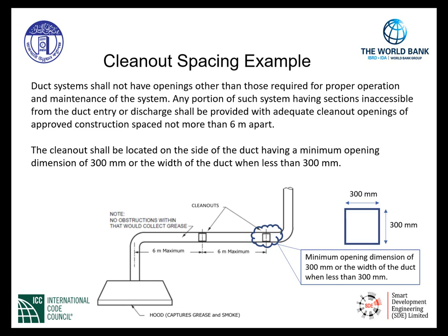Duct systems shall not have openings other than those required for proper operation and maintenance of the system. Any portion of such system having sections inaccessible from the duct entry or discharge shall be provided with adequate cleanout openings of approved construction spaced not more than 6 meters apart.